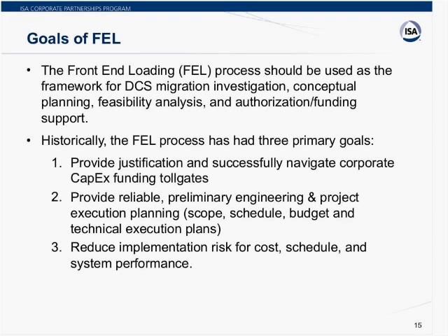Just some goals, and I've probably touched on this a little bit as I've gone along. The overall goal of the FEL process, again, is to use it as a framework. I mentioned DCS migration here. Again, it could be used for a number of other types of control system projects, but it should be used as the framework, the process for doing that initial investigation, getting your arms around what you have and what needs to be in the boundaries of the project, doing the scope boundary definition, the upfront conceptual planning, feasibility analysis of different options, and then finally putting the requisite justification together for getting the project approved.